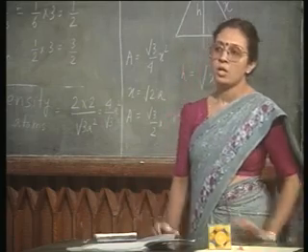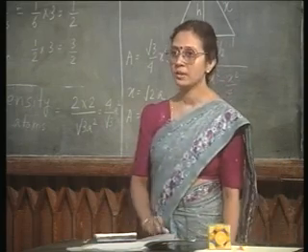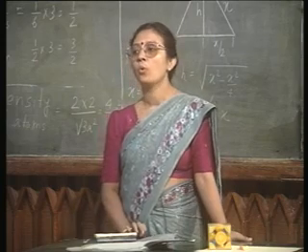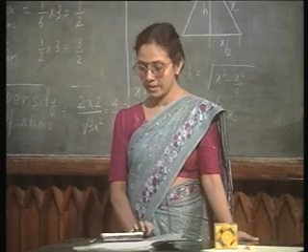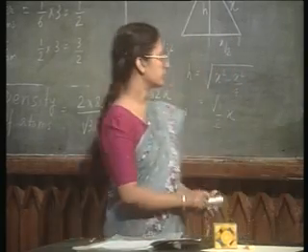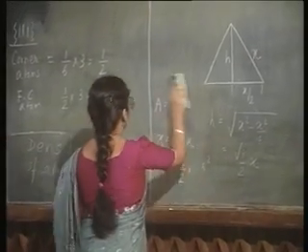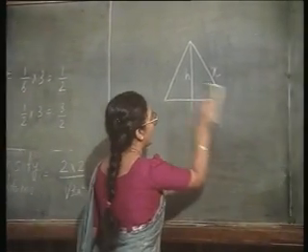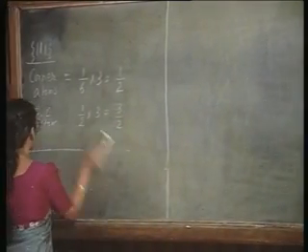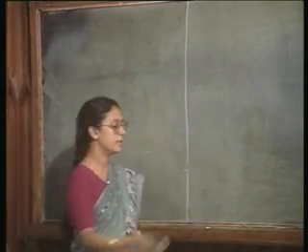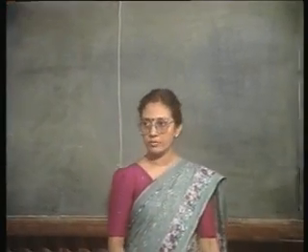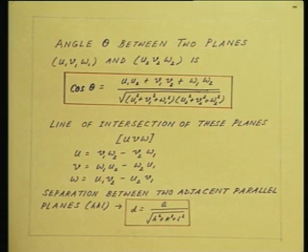Okay? So, let us note this point that the packing density in 100 plane is the lowest. We will look at some of the other properties of these planes, and then we will try to correlate how the material properties are governed by these atomic configurations in the planes.